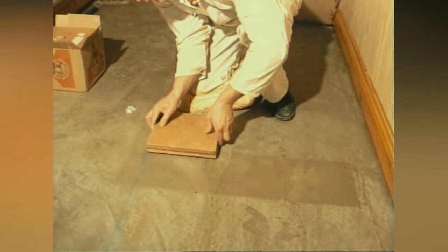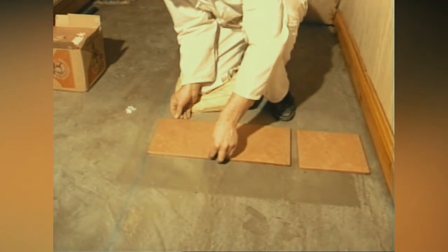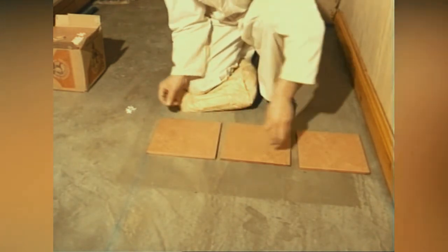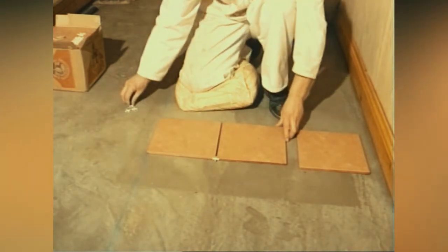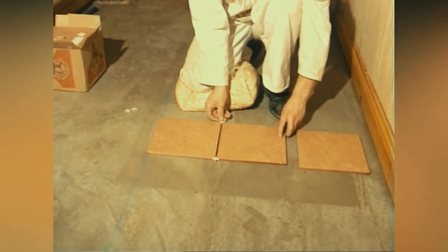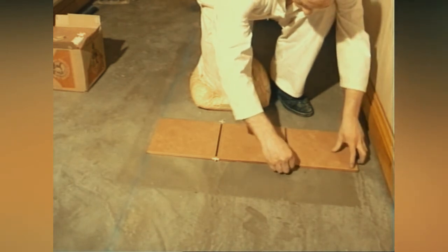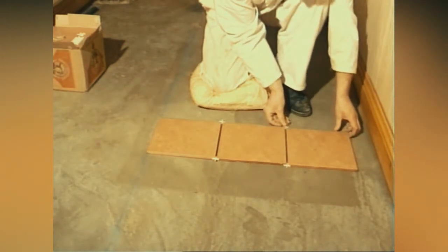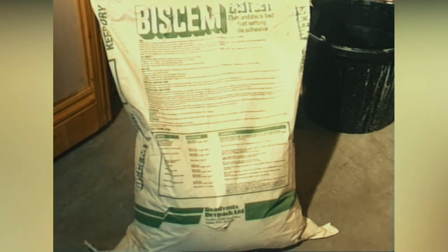Dry lay the tiles from the center line, spacing as required. This is to make sure that there are no awkward cuts around the outside of the room. Floor tiles are generally thicker than wall tiles and are more difficult to cut. Therefore, you need to avoid cutting narrow slithers off floor tiles. Whereas wall tile adhesive is usually pre-mixed, floor tile adhesive generally comes in powder form and needs to be mixed with water. Follow the maker's instructions.